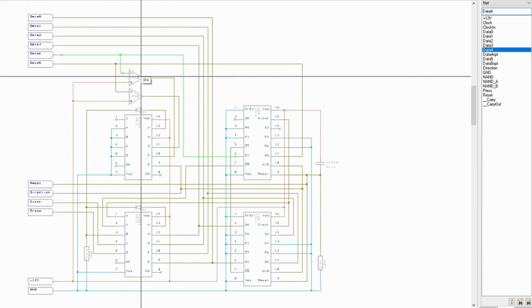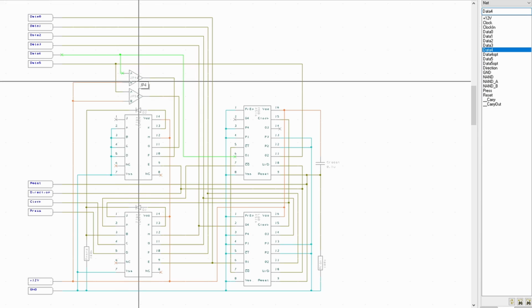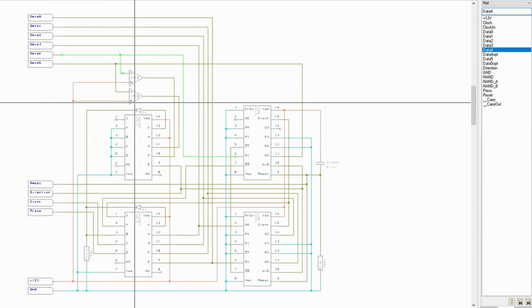And embedding them onto the PCB turned out to be very simple because in the physical world, all these jumpers are just a piece of wire. So I need some mechanism so that I can either connect position A to the common or position B to the common, but not both. And I need that twice. And so I did that in the PCB. Take a look at this.